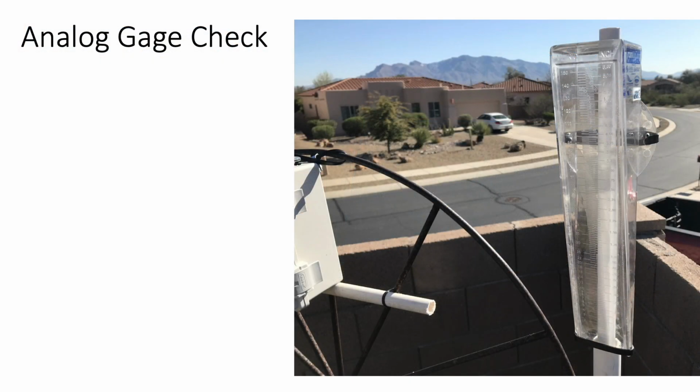In regards to our method for simulating a rainfall depth, let's say I want to calculate how much water to add to the gauge to yield a 5 centimeter storm. Intuitively, I'm going to want to measure a given volume of water, but eventually I'm going to need to convert that to units of length. In this regard, it's very convenient that 1 milliliter of water is equal to 1 cubic centimeter, which gets me closer to my desired unit.